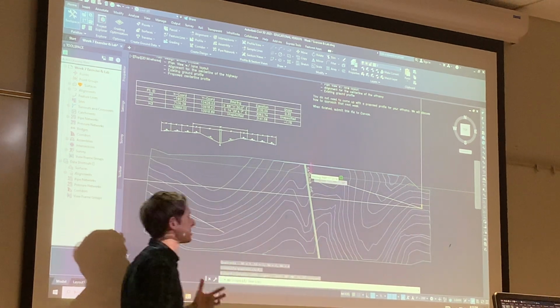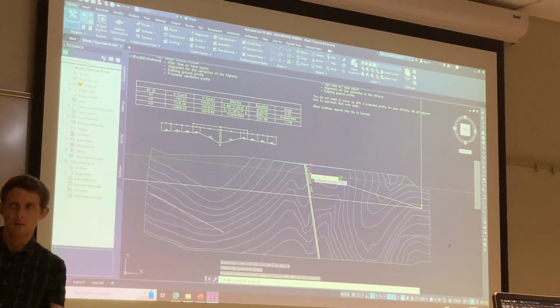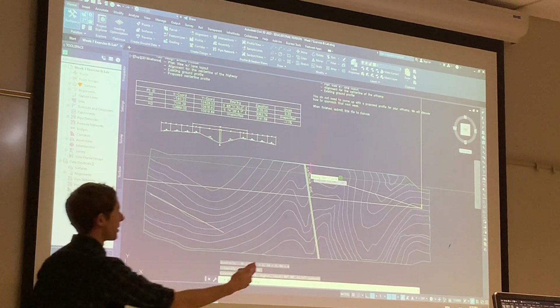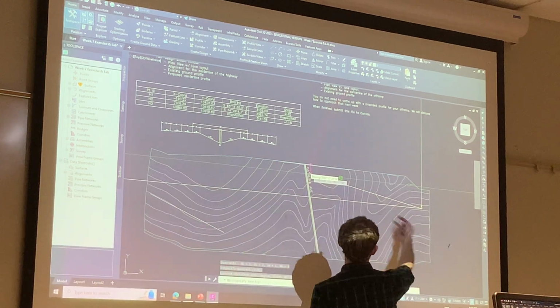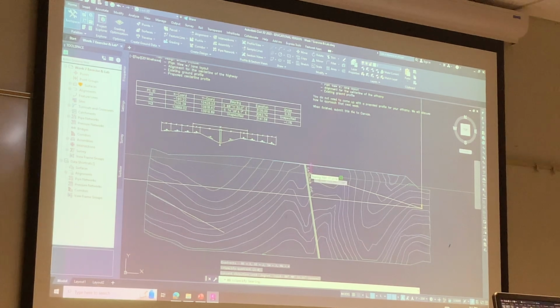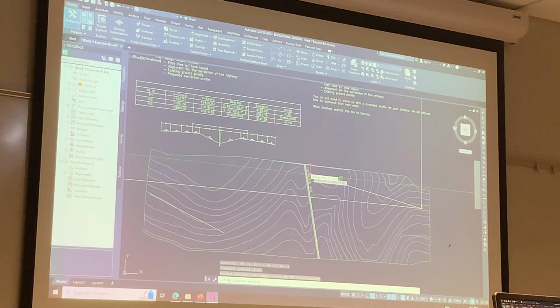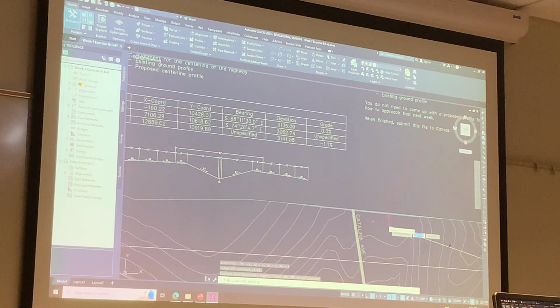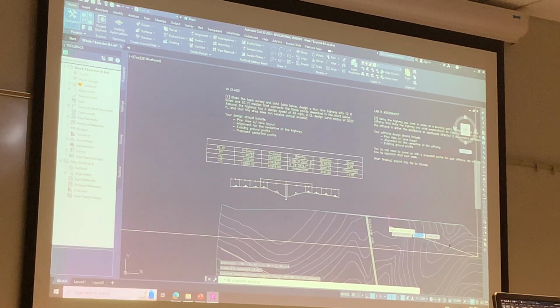So it's not 100% correct, and actually if I was to create an alignment just with that line, the alignment would be going the direction that the polyline was drawn, so it would be going this way. But I can fix that in my next step after I draw the line. So let's see here. I select the quadrant.